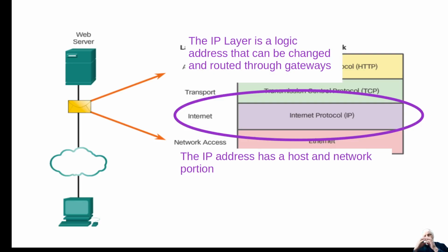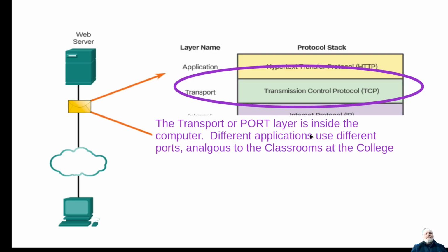mean that they're actually kind of set in the chips. And years ago, when you bought it, it came with a hardware address and you could not change it. Nowadays, a lot of newer systems will allow you to change the hardware address after the fact. Some of them still don't. But they have that physical hardware address that, like I say, on a lot of systems like your PLCs, you can't change. But they have to be unique for everything on the network. And then we have the internet ones. Those have to be unique for everything on the network also.